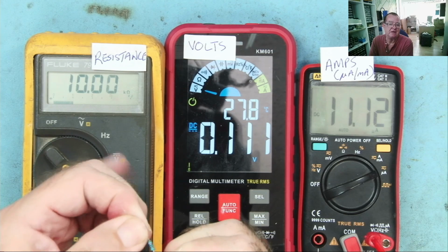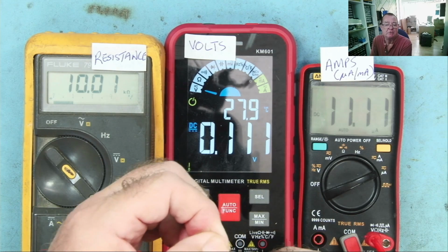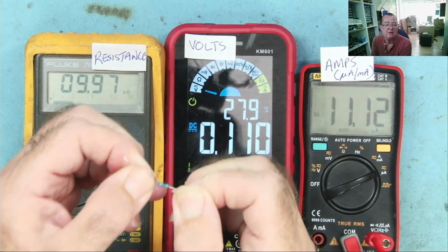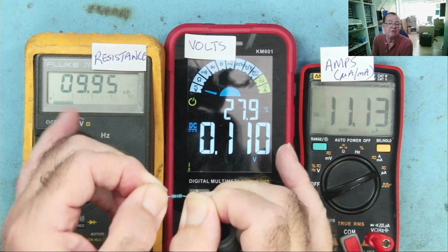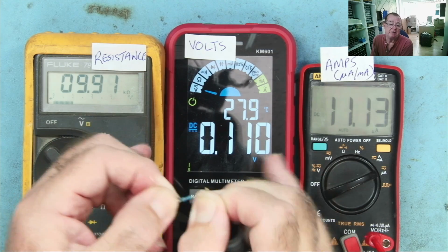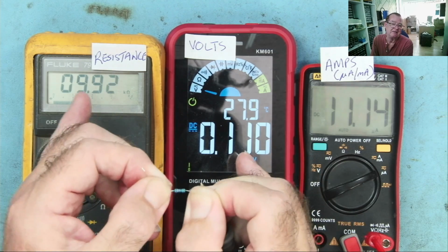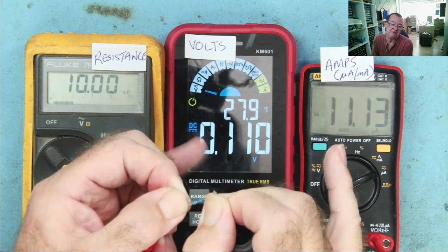1.11 in fact, okay, that's reading 10 now. And on this one, the 11 microamps is the current that's flowing through this resistor. So this meter is measuring that current, 11 microamps. It knows its voltage because it's generating the voltage. And you can see that if you divide it yourself, that's how it comes to 10k. You can see, although the decimal point, the digits are there.